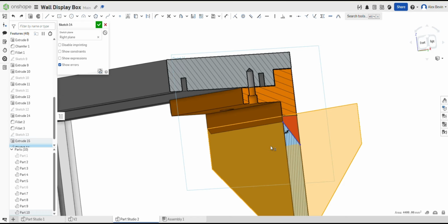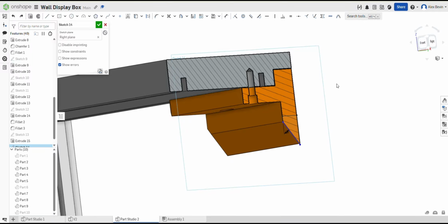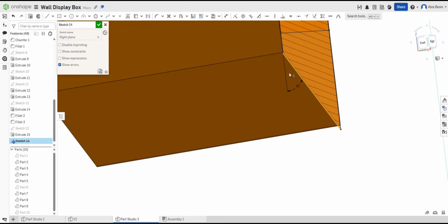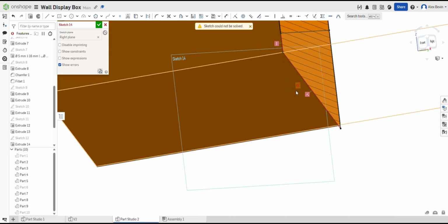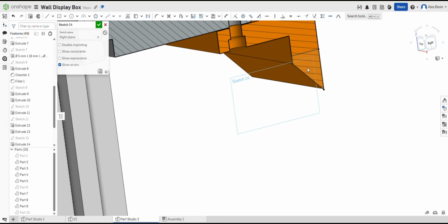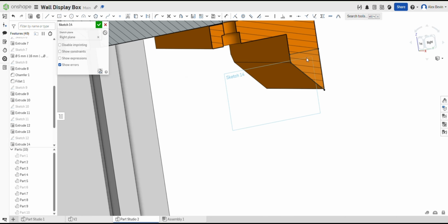Rest of bottom cleat. Clearance cut plus holes plus finish plus checks. Alright, now that the bottom cleat body is modeled, we're going to do 3 things. 1. Remove the clash. 2. Add the screw holes. 3. Soften the edges where it matters.